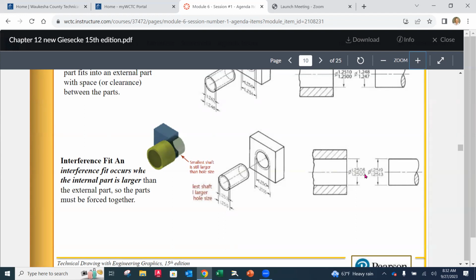So somebody's gonna be like, okay, what do you want? What's the tolerance on this? And you'd be like, well, oh, okay. I caught that on some people's drawings. When you're going in, if you don't change the number of decimals to a 2 or a 3-place decimal, and you put 4 decimal places on everything, your title block isn't covering anything. There's no tolerances there. That's a problem.